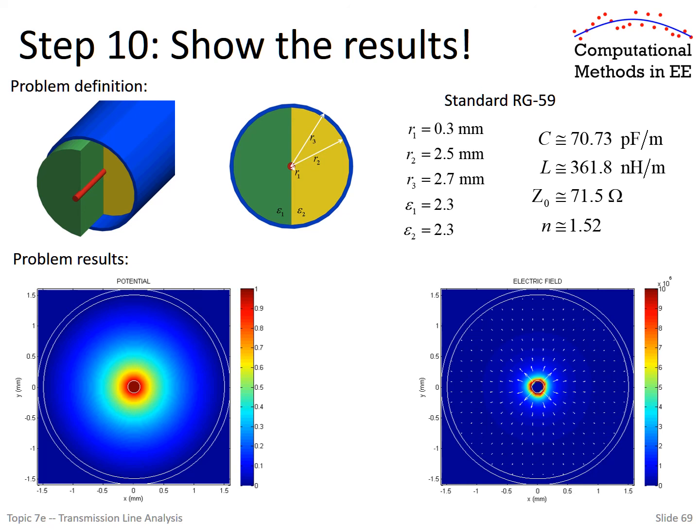Capacitance is in the tens or hundreds of picofarads. And we need to do per meter because we're only analyzing the capacitance and inductance in the cross section. Well, the length also changes things. And so if we had the length, we could calculate total capacitance and total inductance. Since we're only analyzing the cross section, it's a distributed inductance and distributed capacitance.